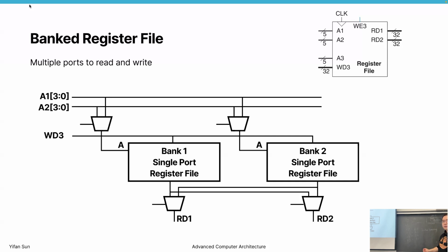Because more likely we're going to do something like R1 equals R1 plus R0. So these 2 registers are likely to come from 2 different register banks. And for most GPUs, 2 banks are too small. Like they have 4 or 8 banks, or even more. Okay, they can have many different banks. It's really a parameter. The more die size, the more banks you have.